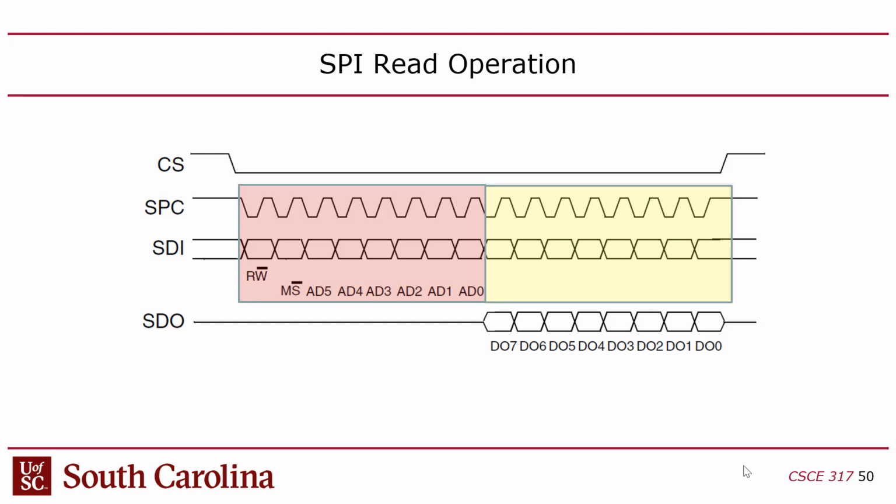When you drive the clock up and down, it sort of rolls up and rolls down, looking kind of like a sine wave, because you have to charge and discharge a capacitor. A lot of times you'll see this gentle up and down on timing diagrams. To me, this just makes it harder to read. I don't like this style.